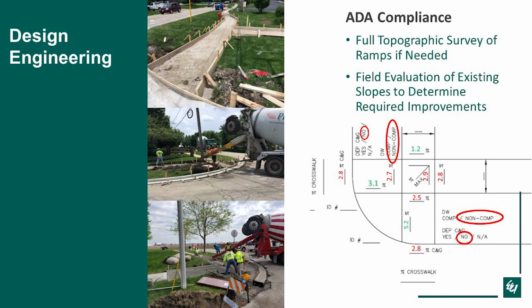ADA compliance. Up there is an example of a sheet that our field guys take out to the field. They use their smart level, start measuring the slope of the squares, and we fill out these corner sheets and come up with the best design for replacing those ADA ramps.